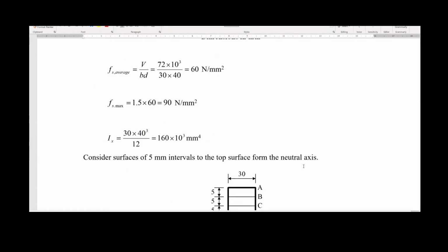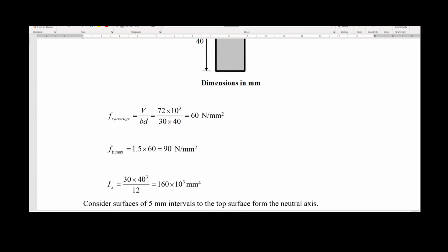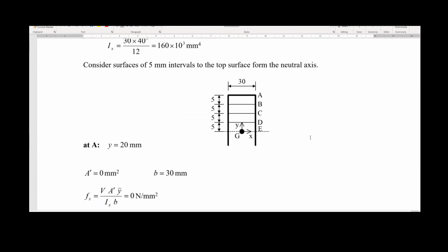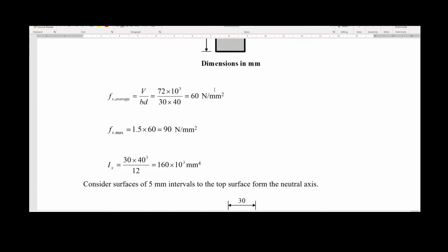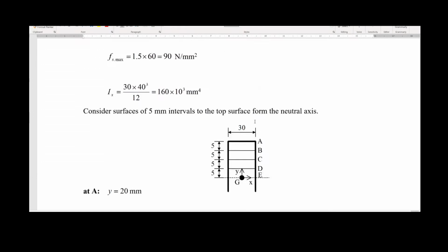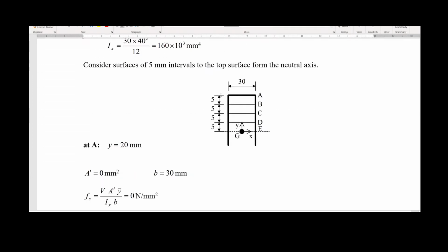And after that we do what the third point is asking, because this is point A, this is point B, and the next point, point C in the questions for this example, is to divide the cross section from the neutral axis. So we have half of the cross section only here. Because the cross section is in total 40 millimeters, half will be 20, and this 20 will be divided in 4 different intervals. From the neutral axis to 5, from the neutral axis to 10, from the neutral axis to 15, and from the neutral axis to the extreme, which is 20 millimeters. And we can call, for example, these points with letters. This will be A, B, C, D, and E.